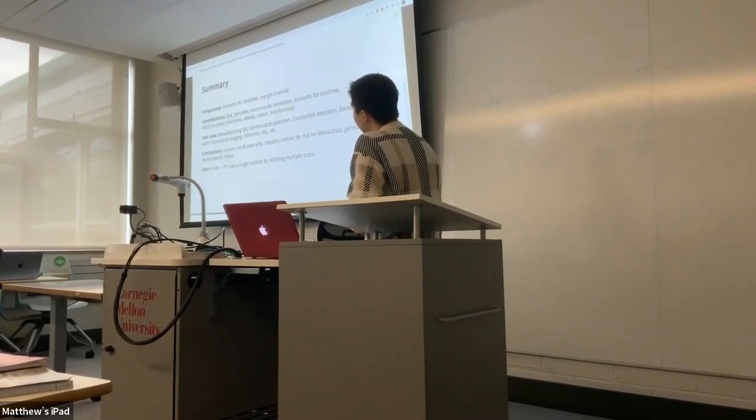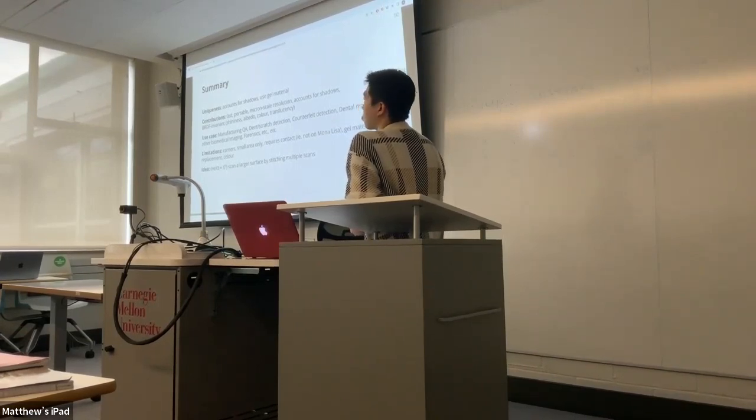So if I were to hold something up with the GelSight, this object might be pulling down on that GelSight pad and deforming, or basically shearing, that pad. So imagine taking one of these GelSight pads and painting it. We also add maybe a grid of dots. What the camera would see under natural conditions is just a grid of dots on the sensor. Now, if you press that down, maybe at an angle, those dots may shift somewhat. So it's a certain amount of shearing, and perhaps it can be used to identify the forces.